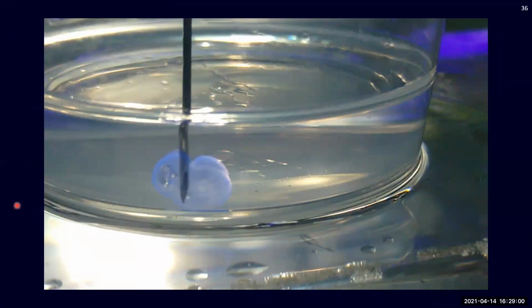And initial tests when I was running the first experiments for this showed that there was actually some resin and/or bubbles inside the model. So some of them were sinking much faster than I would predict, and some of them were sinking much slower. So instead of using opaque plastic, such as the ones that are printed here, I 3D printed using a transparent plastic instead, so that I could see inside the model and make sure it was fully clear, and also that there were no air bubbles inside.